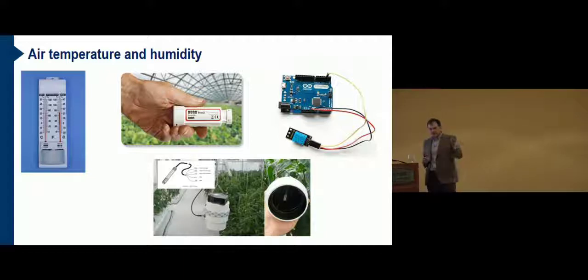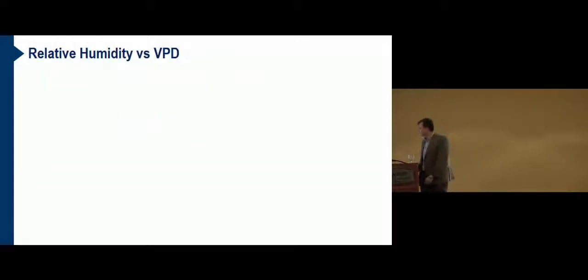So an aspirated, shielded sensor needs to be used. When you're measuring the light, the sensor must be positioned in a place where there's no direct shadow hitting on the sensor, and the sensor must be kept clean to improve the accuracy of the measurement. So we have a more representative measurement of the light over the course of the day.